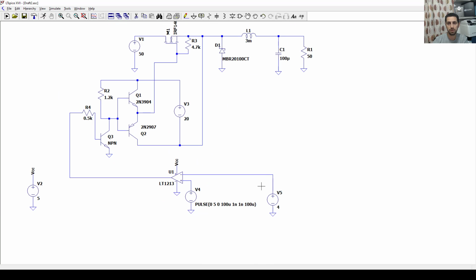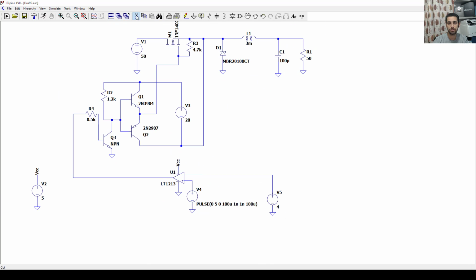Okay, so that voltage, I don't want it to be the main controller, because that voltage is controlled by me. I want the feedback to control it, or supply it. So that's why we will get another resistor. So how do we get the feedback now? We can get a feedback by a voltage divider from the output voltage. So here's the output voltage.